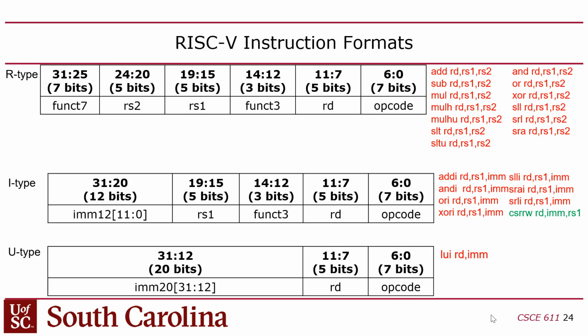Yes? You have the shift amount. Yeah, exactly. The shamt. Yeah, there used to be a shamt field. And that was one of the criticisms of MIPS. People were like, that shamt field is all zeros or don't cares 99% of the time. Because even when people are doing shift instructions, they're usually doing variable shift instructions. The shamt was only for a constant shift amount, right? So it was a waste. That was a boneheaded decision to put a shamt field. So we're going to repurpose those